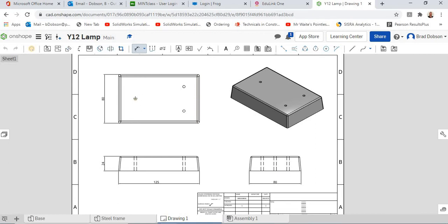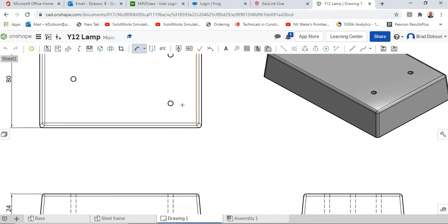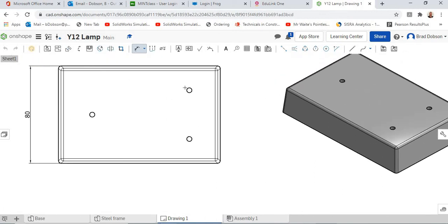We then need to think about putting some of the dimensions of the hole centres, but again it's quite tricky at the moment because we've only got a circle. So what we could do with is putting some centre lines in there. To do that, it's very straightforward. Up this top section we've got our centre lines. So I'm going to put a centre mark. All I then do is select each of the circles, and you'll see it'll put a centre mark on there.